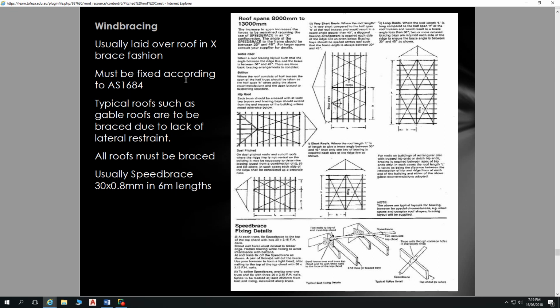The wind speed for an area can be determined from, as we saw on SA Map Viewer last week. So we go on SA Map Viewer, and we can work out how we can typically get that wind speed. That wind speed will inform us via the timber framing code of how many kilonewtons of force are going to act on the side of that building in a racking force.